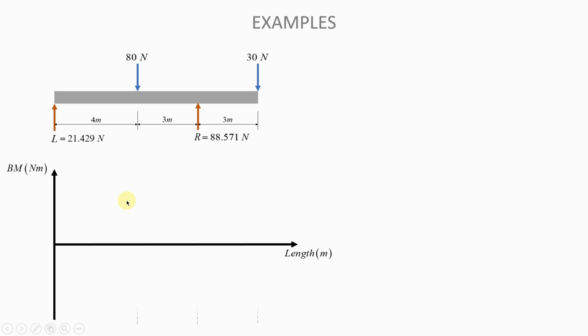And again, we have our points of interest as I explained earlier. The start and the end of the beam are always points of interest, but also everywhere you have a load that is introduced is a point of interest. So we have that like that.